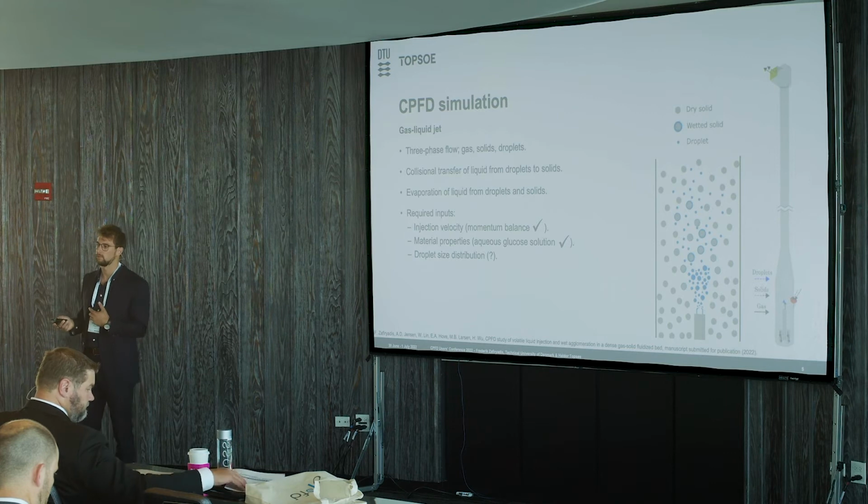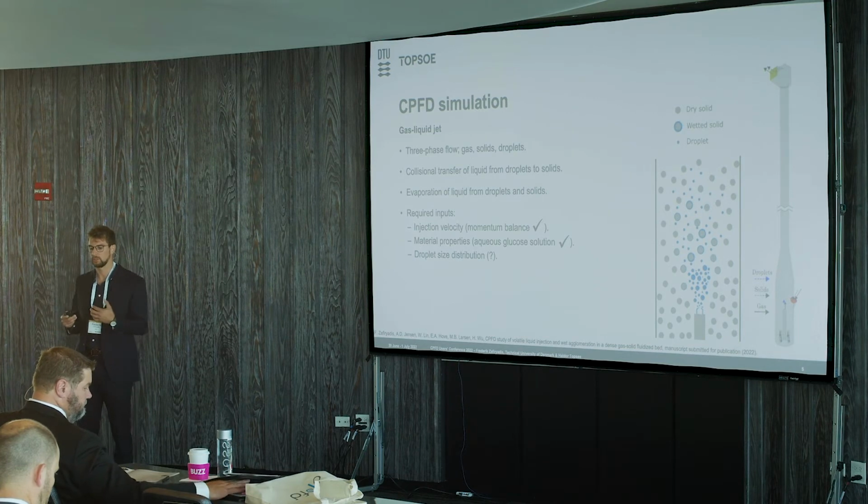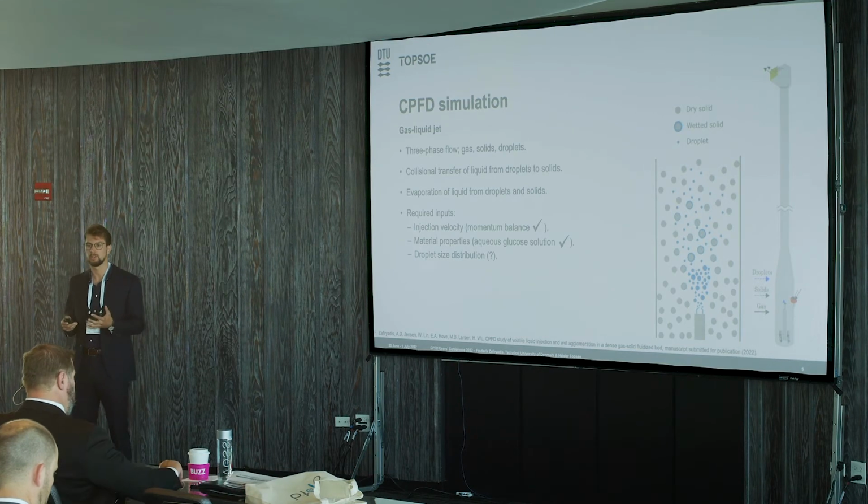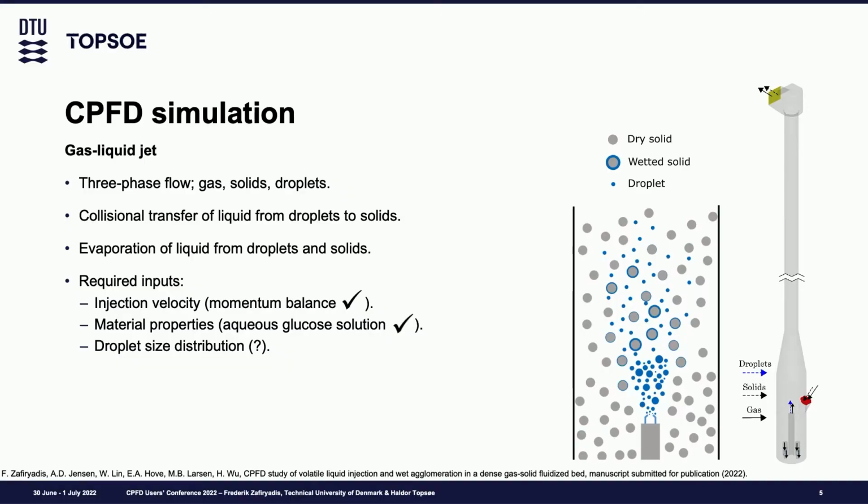There's actually been a lot of work going on in terms of discussing whether there is atomization at all when you're injecting liquid into a dense fluidized bed. But in this case, we're working with a Lagrangian approach. So within the framework of Barracuda, we need to specify what the droplet size is going to be, even though it might not be completely realistic. So we've been doing a lot of work trying to figure out the best way of doing this, such that it's the most consistent in the way that we're working.